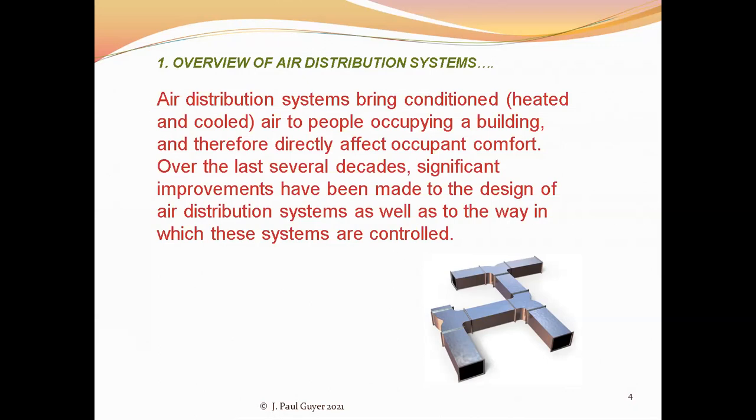Probably there has been a reduction in the load on the building's HVAC system, some retrofitted windows or retrofitted insulation, this sort of thing, that has reduced the load on the air conditioning system. Therefore, you may be able to make some changes to the air distribution system to recognize this reduced load that's required because of these other changes that have been made.